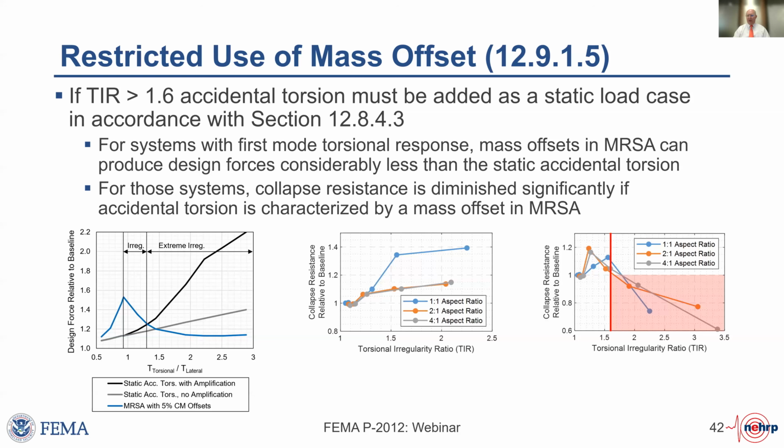There is an interesting finding from the project. We found that using one method that you might think is precise would help. It makes the problem worse. The big idea with accidental torsion is that we can't predict perfectly how our system is laid out. So there could be some twisting in a system that is nominally doubly symmetric. It could still twist. And so the long used code rule is that we need to consider a 5% offset of the lateral force from the center of mass.